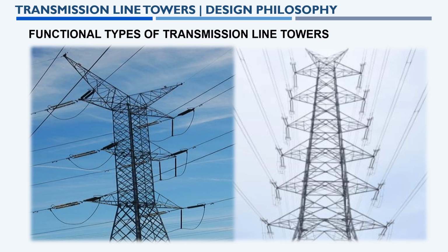Here you can see that tension insulators are used on both sides, and in the dropper connecting here on the right hand side, you can see both side conductors are connected using the dropper. Sometimes some vertical insulator is also placed here.